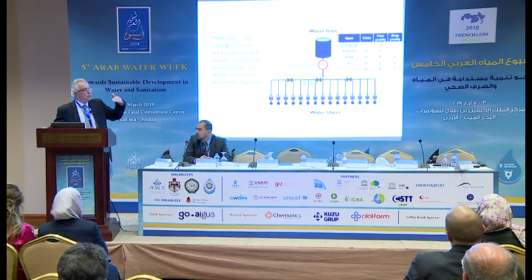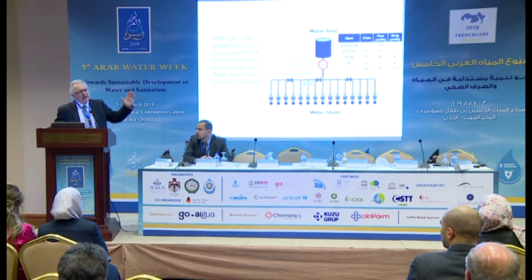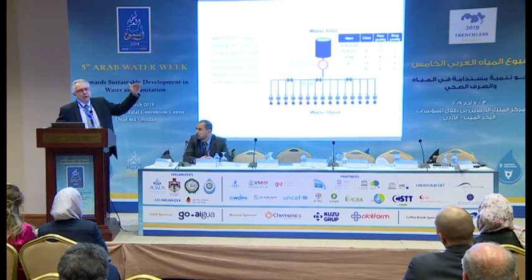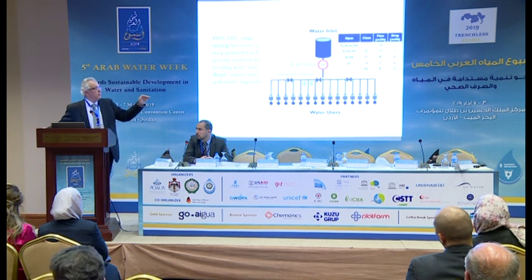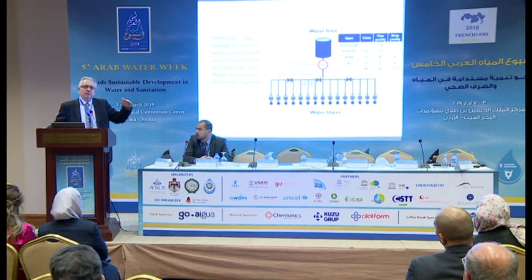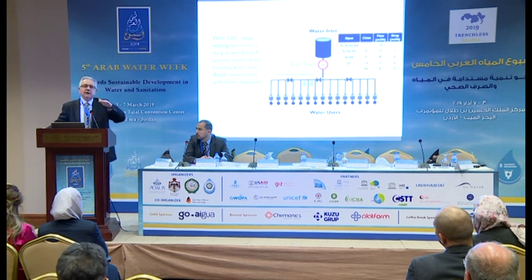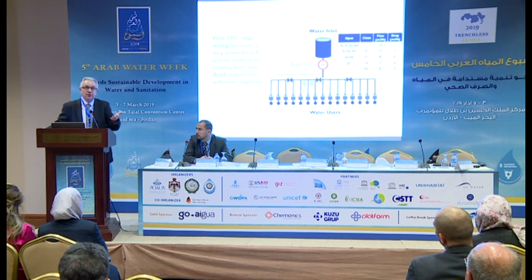As we close each step, we are reducing the water going into this area. The beauty of this is that we can do it very easily because all the customer valves are closed, so we don't have consumption. So any water that is lost is either leakage or unauthorized consumption.